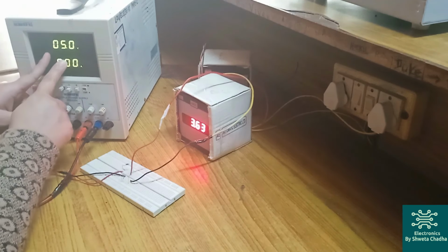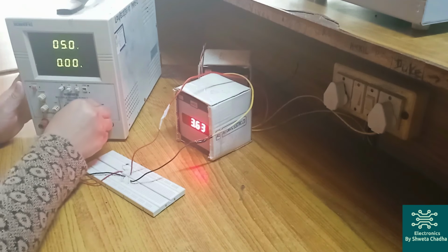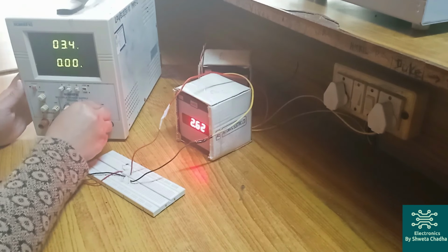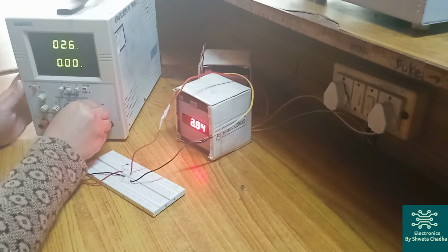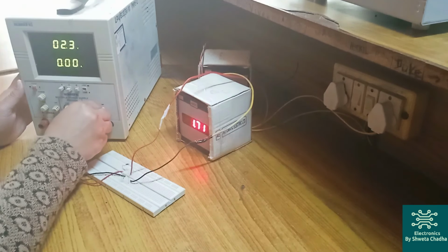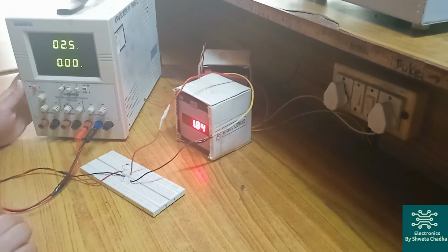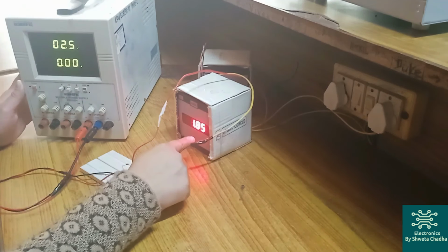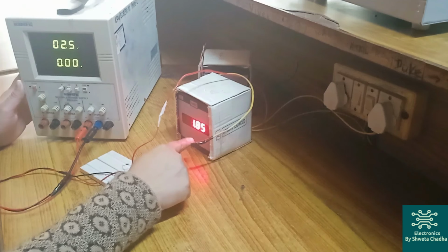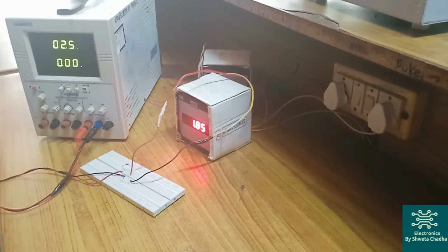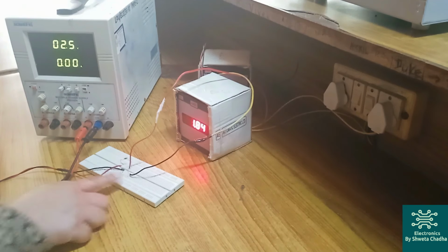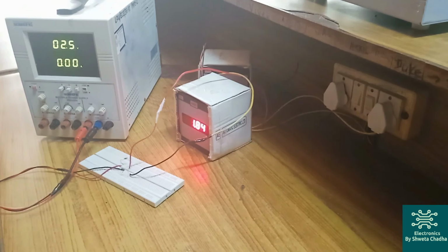So this must be set at VTH. What was VTH? 2.5 volt. Let me decrease its value till 2.5 volt. Now you can observe it: with 2.5 volt VTH, we have got approximately the same value, 1.8. Hence, the current flowing through RL in step number 1 and step number 4, that is Thevenin's equivalent circuit, comes out to be equal to each other. Hence, Thevenin's theorem has been proved.